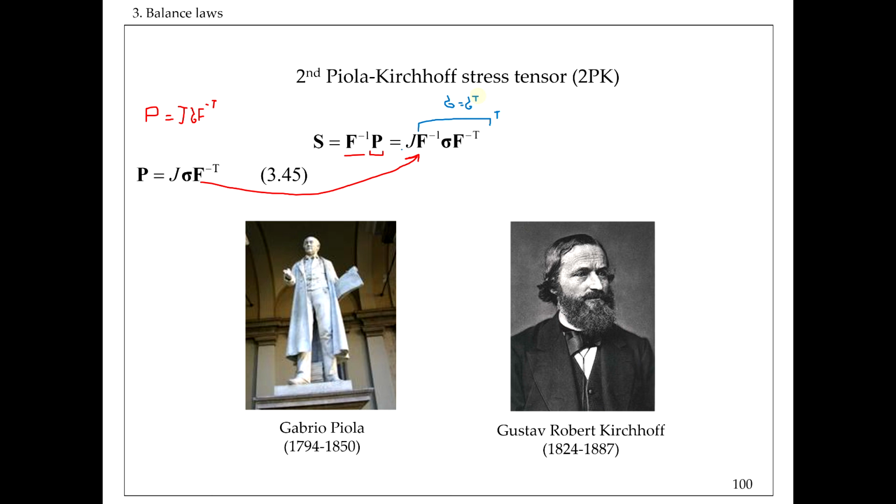That's a good exercise that you can do, and therefore this transposition operation returns the same result if done properly. And so what is important to say here is that the second Piola-Kirchhoff stress tensor is symmetric. That was one of the motivations for defining this new measure of the stress tensor.